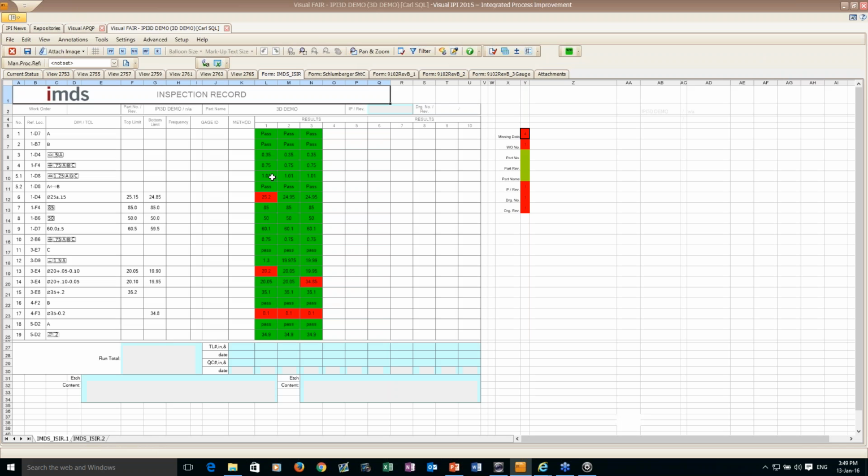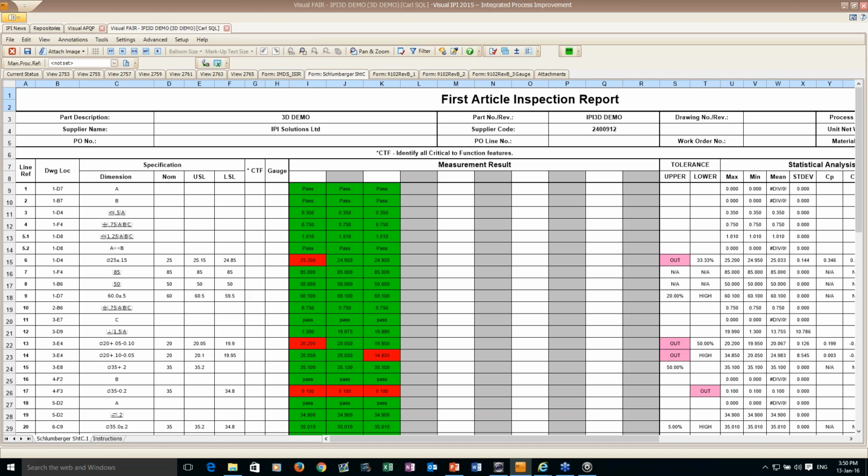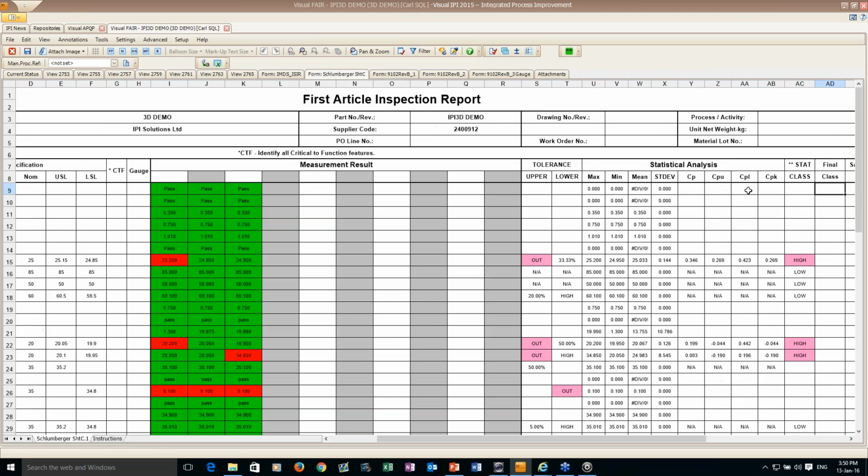My initial sample inspection report, commonly used within the medical manufacturing market. And obviously then my typical oil and gas form. So 3 sets of results, but also continuing to bring those results in as part of the process. You're inspecting it as part of the process. This particular document then starts to calculate my CP/CPK values, my standard deviation, my average across all of that.